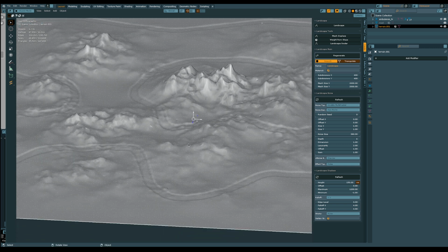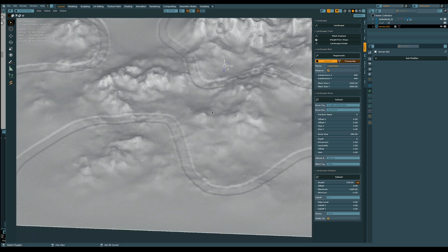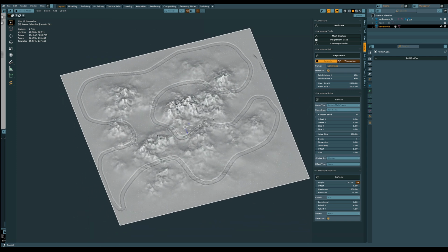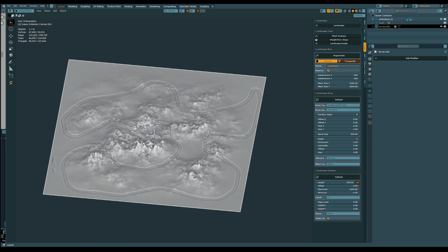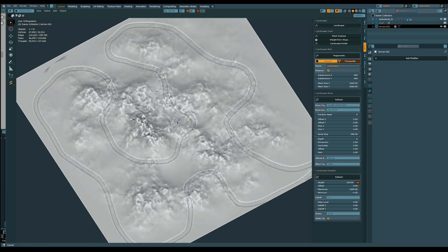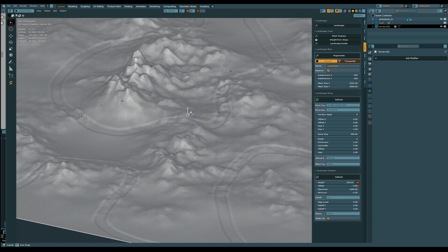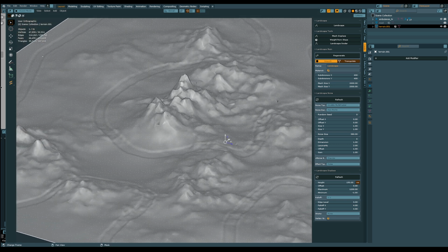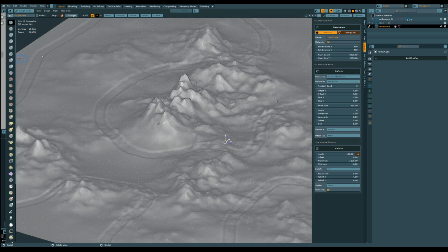And I'm gonna be showing you how to add details, to add extra stuff before you slice it. You have to do that before you slice your world or your map or whatever you want to call it, the terrain, your racing track or whatever you want to do it between the mountains. And go to object mode, sculpt mode, and look for the smooth right here.